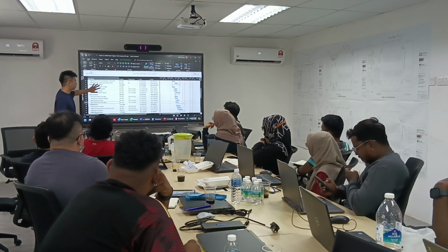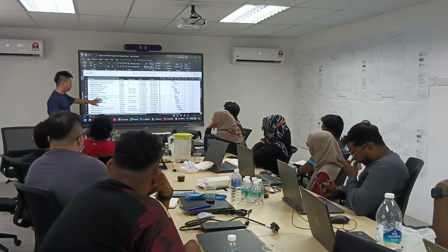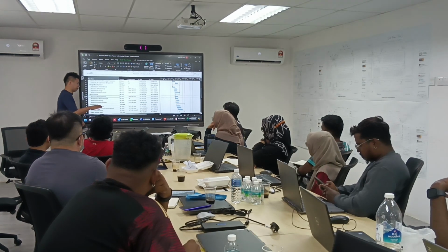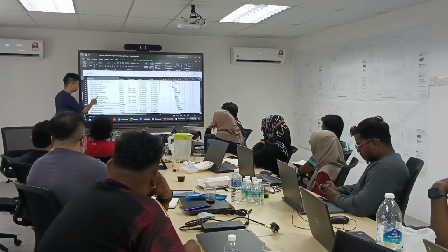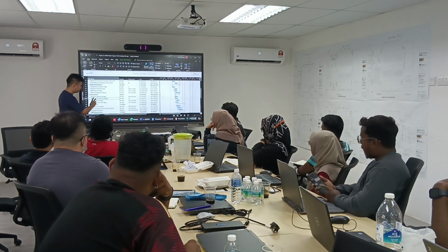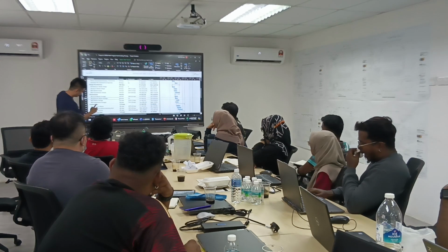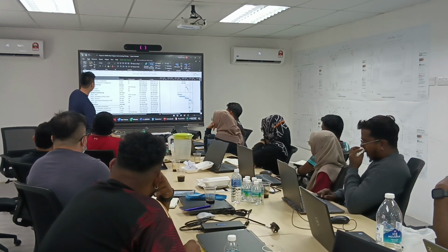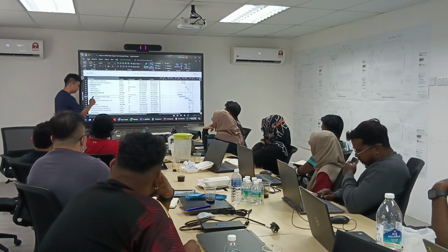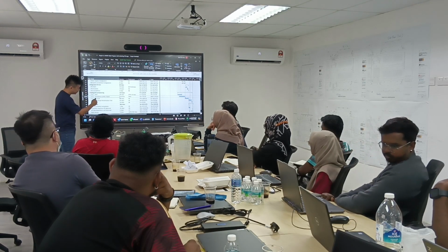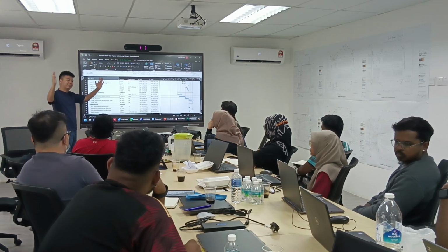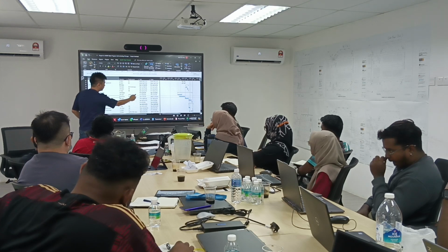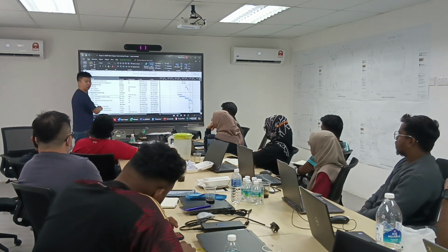If you have a good planner, they can give you a program that is super detailed and very helpful for you. Imagine, I don't have that right now because I thought this was the full one. If you have a very detailed one, for example under MEP work, let's take the simplest one, CX level 2. With the detailed program, under CX level 2 you can see each equipment. What is the date range we want to complete it in? And what is the predecessor, meaning what is holding it up so it cannot complete?